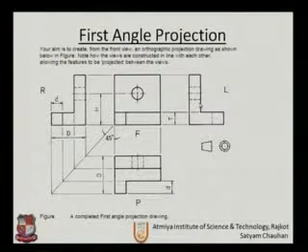The hidden line means we have one object here, and from the front view we are drawing a 45-degree line, and by extending those projections we can obtain the top view. And then in the last we have to show the height, thickness and related dimensions in the respective views, and hence we can complete the first angle projection drawing.